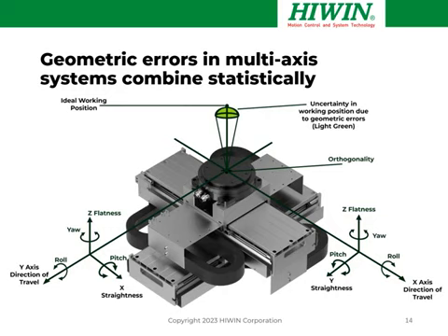And that drives cost. What motion engineers do is we add them statistically. An RMS, or root mean squared calculation, is the accepted industry method, and it's a much more realistic estimate of performance. And this is really the foundation of the error budget. In other words, how do I predict the motion system performance at my tool point, or my ideal working position or point of interest?